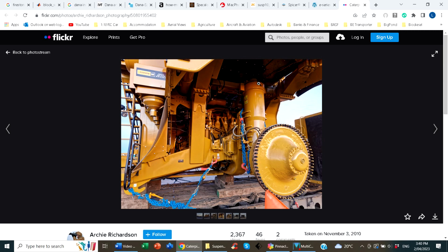The gas provides the springing, the oil provides the damping, and they're used extensively in haul trucks because they can carry heavy loads. Now you can do that as a specific unit, or you can just take a hydraulic cylinder, add some valving and an accumulator and achieve the same result.